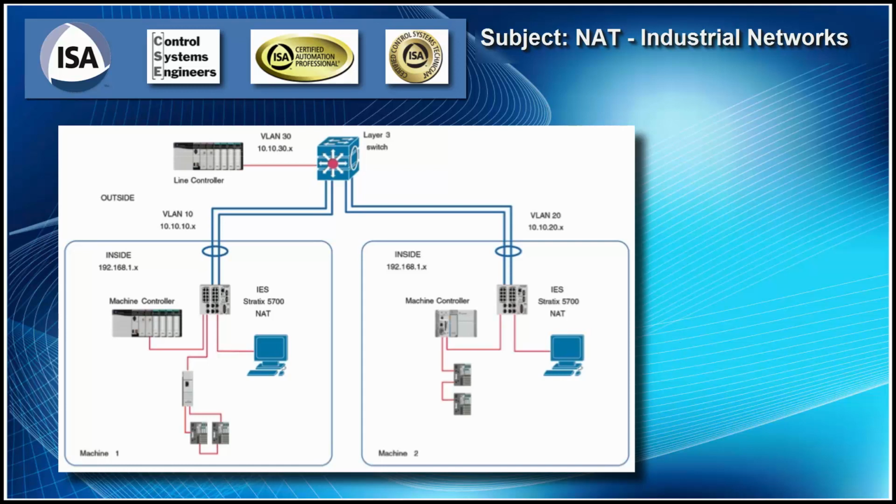On critical process control, you don't care if you missed a glitch in an analog readout. You just get the next analog readout. And this is where UDP is faster and is used for a critical process. So let's take a look at UDP and TCP and see what the difference is and why we use these.